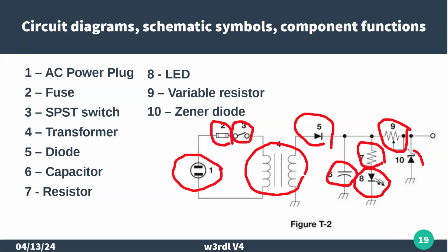And then we have a Zener diode. And if you remember, I mentioned before, if you operate a diode in reverse at some voltage called the Zener voltage, it will break down and conduct current in the opposite direction. So we use those as a voltage reference source typically. So in this case, say this Zener was say 5 volts.